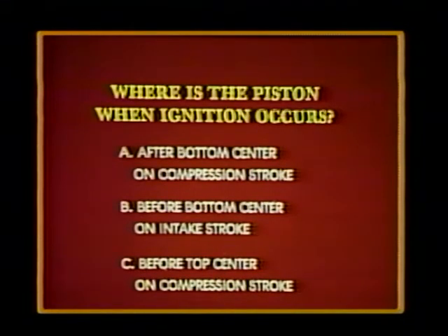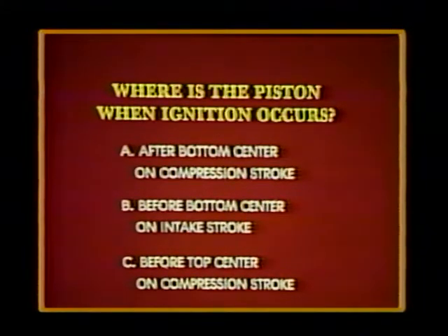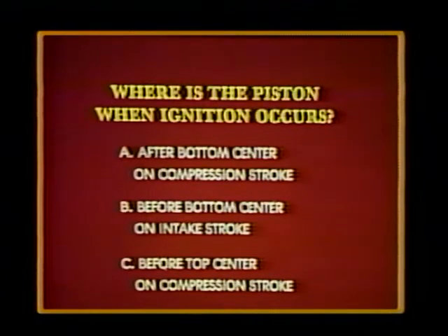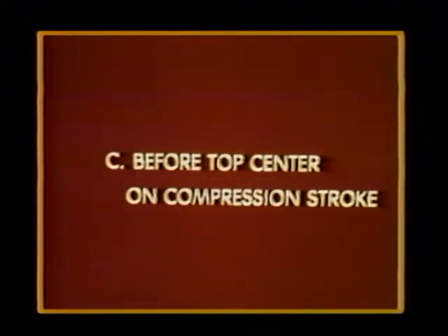Finally, where is the piston when the ignition spark occurs? Is it after bottom center on the compression stroke, before bottom center on the intake stroke, or before top center on the compression stroke? The correct answer is before top center on the compression stroke. The mixture is ignited when the piston is moving upward and is about 30 degrees before top center on the compression stroke.